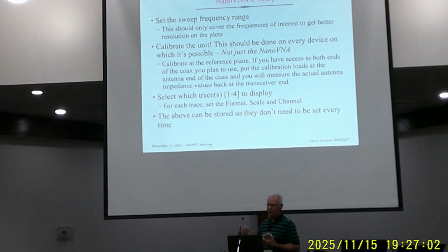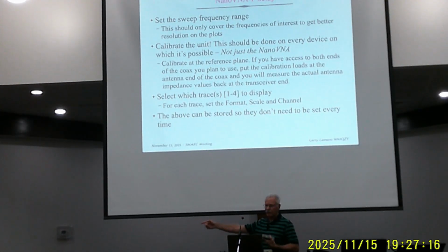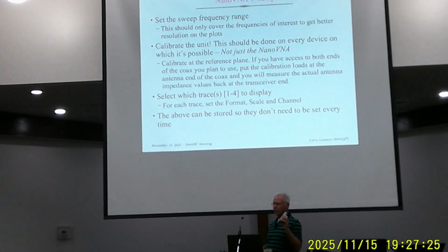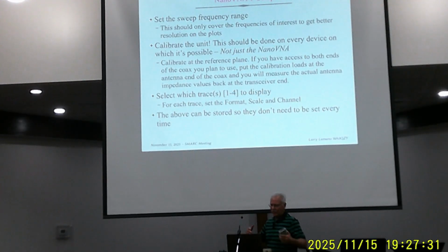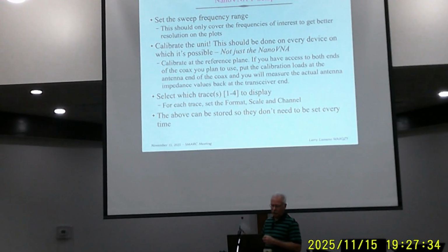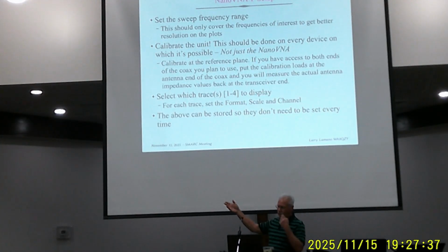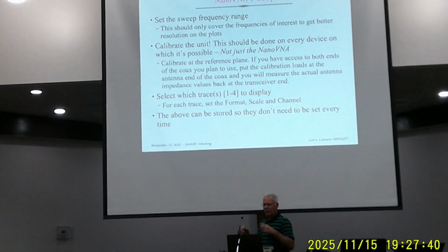Any transmission line is an impedance transformer. And it's kind of weird, but this is a crazy example. If you have just a pure 100 ohm resistor, and you put that right here, it'll say R equals 100, X equals 0, right? There's no reactance, it's a 100 ohm resistor. If I put a quarter wavelength transmission line between that 100 ohm resistor and here, it'll show it's 25 ohms with no reactance. That'll show as a 25 ohm resistor, even though it's clearly 100 ohms, because of the transmission line. The coax completely changes those, and in between there, that 100 ohm resistor will actually look like it's partially reactive, capacitive, or inductive. That's all because of the transmission line effect of that cable.